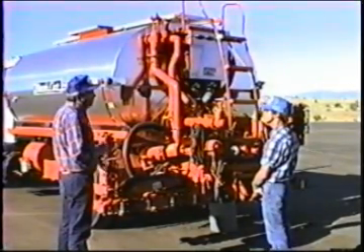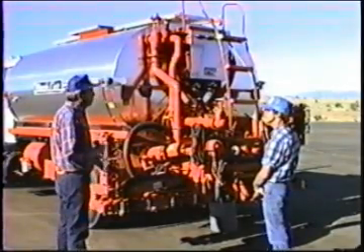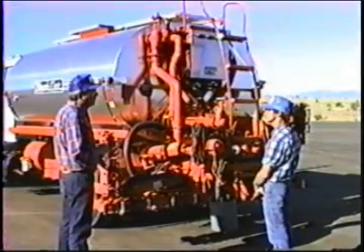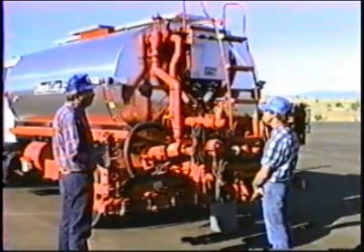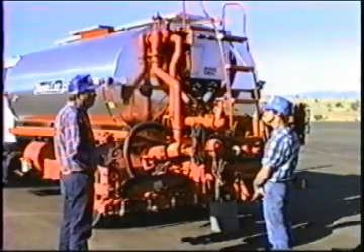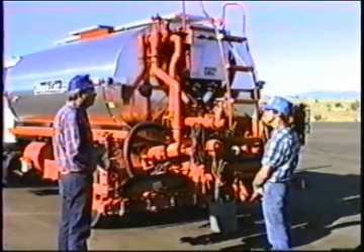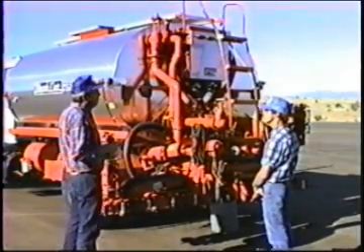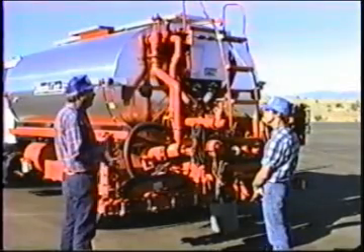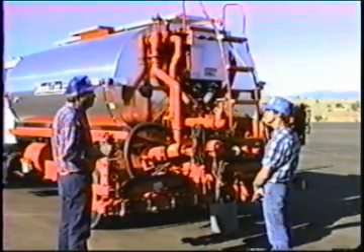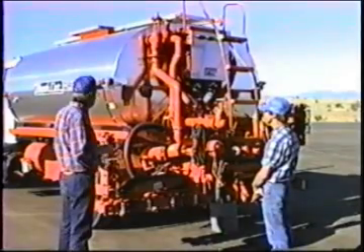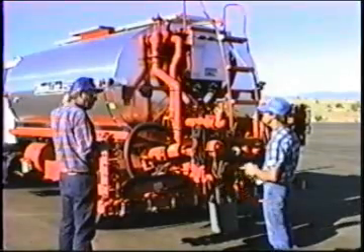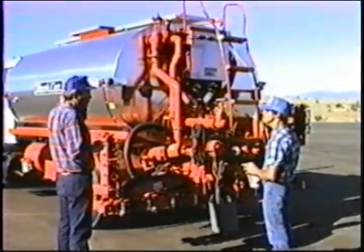First of all, if we can flush it, that's the best. That is, if at the particular loading facility, we can load it with some asphalt material that's less than 200 degrees. Say we can load it with MC250 and the material is only 180 degrees, that's ideal. We would load the tank, circulate the spray bar, and offload it. That'll get the moisture out the easiest way. It actually gradually cooks it out of the material. If we can flush it, that's great. We flush it and then we load the hot material. If we can't flush it, then our only choice is to load the hot material.